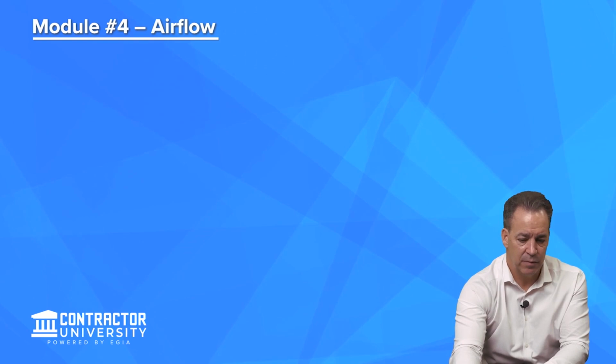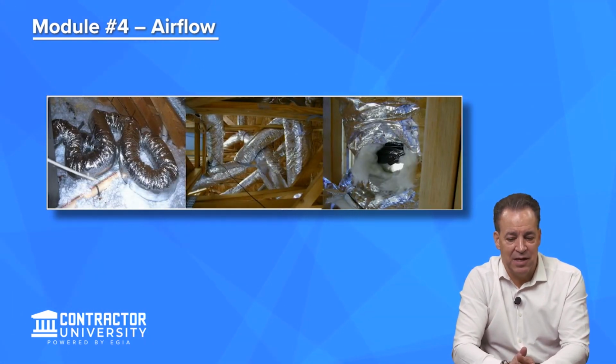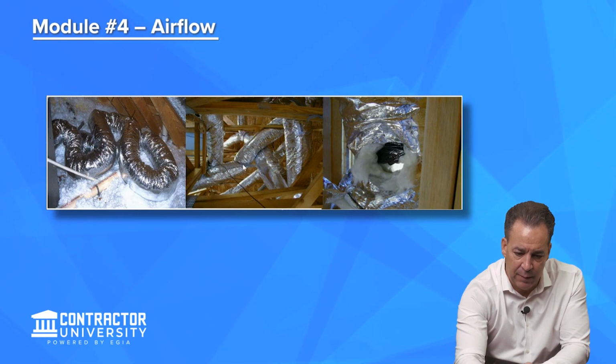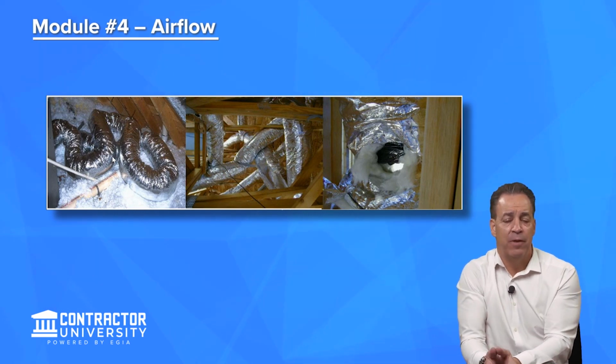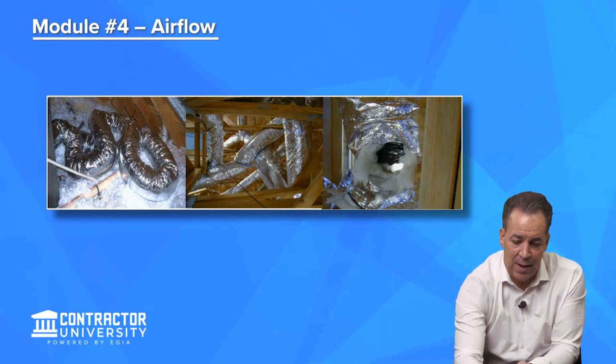Doesn't mean that it is, right? And so here are some pictures of some of the types of things that you're going to see out there. The snake of the flex, running all over the place, not supported properly, pinched off in some cases right here. Extra flex running all around, like I told you. Right on the box, the manufacturer says don't install flex any longer than 15 feet. But you're going to see that that's what's happening here.